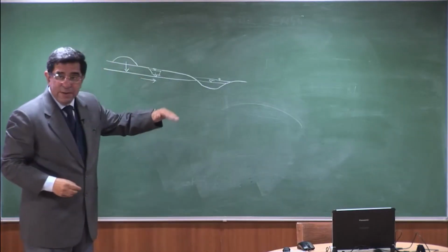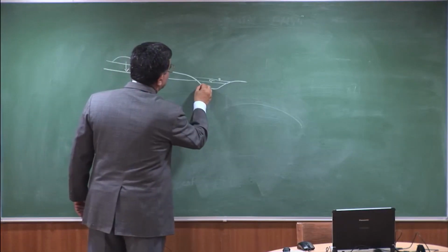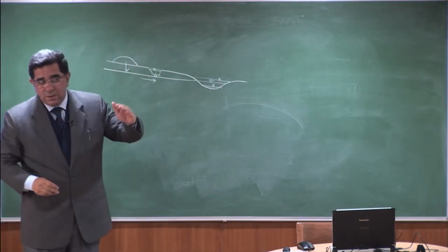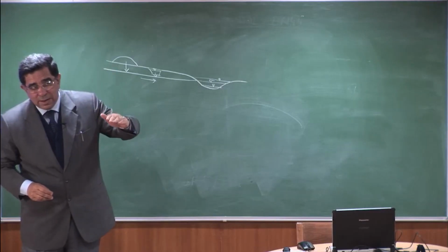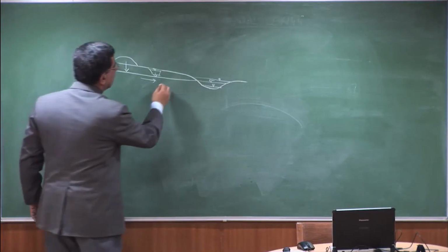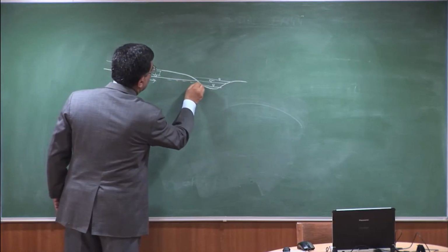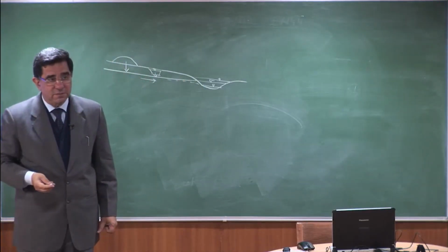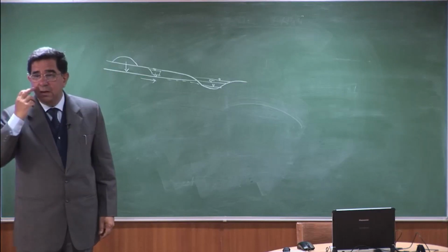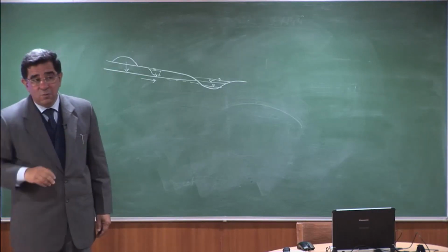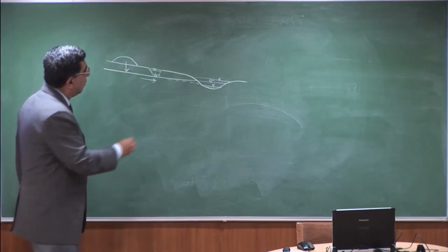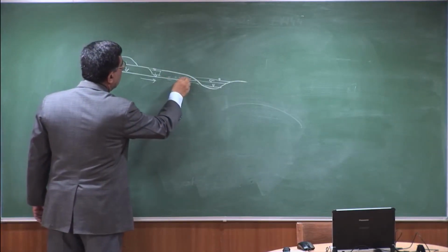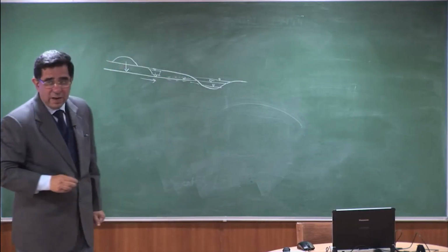During the lean period, that means during the summer months, the water level may fall here and the water table would begin to get lowered as it discharges into the river. During the floods, a recharge takes place. That means the water level in the river becomes higher than the groundwater table outside. So in such cases, the water can flow in this direction as well.